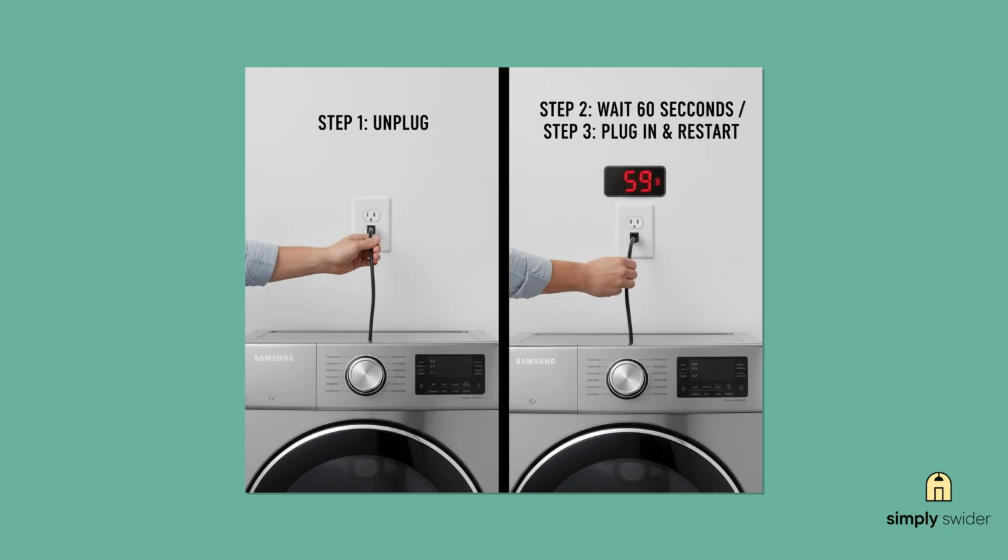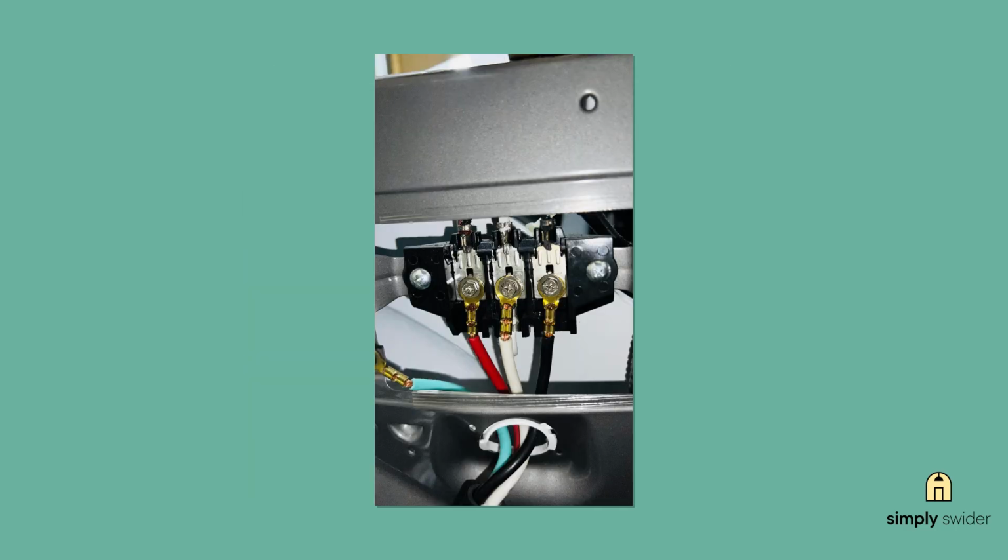But if the error code comes right back, you're dealing with a more serious electronic problem. This usually means the main PCB or user interface has failed, and that's where you might want to call someone like me because we're getting into the expensive repair territory.